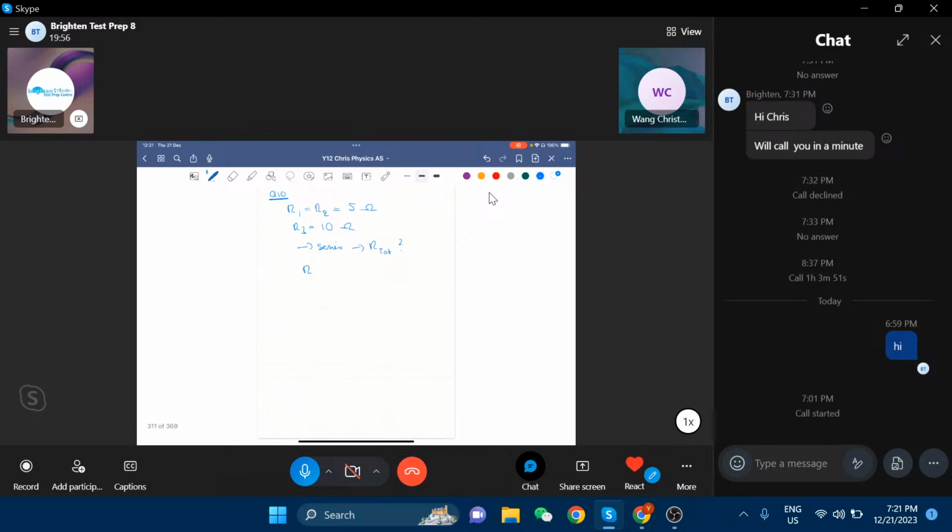That's easy series. It's always extremely important to say what am I talking about? Am I talking series? Am I talking parallel? Sometimes you have to figure it out in the scheme of a bigger circuit, what is what, but we are coming to that when we deal with more circuits in more detail. So the RT is, of course, R1 plus R2 plus R3, as it says, straightforward.